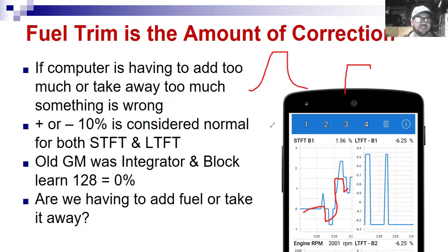Now, this is one of the things that can get cleared out if the vehicle's battery is disconnected too long. Sometimes on some vehicles, even with the code clear, or some vehicles have a fuel trim reset function there as well. And so you might disconnect the battery or do that fuel trim reset, and now the car's running a little differently as the computer has to relearn the amount of fuel trim correction for each cell in that graph.